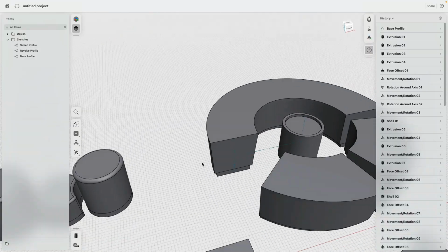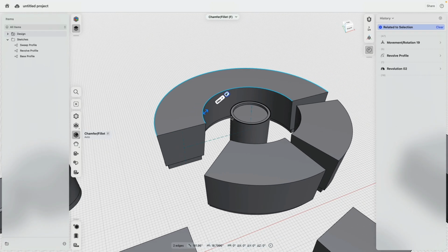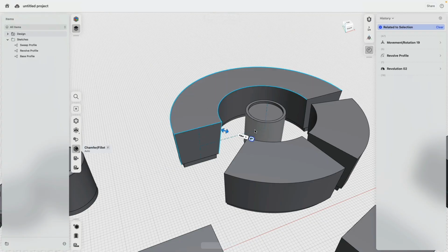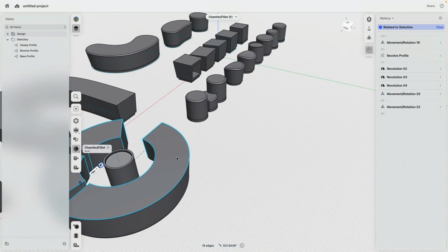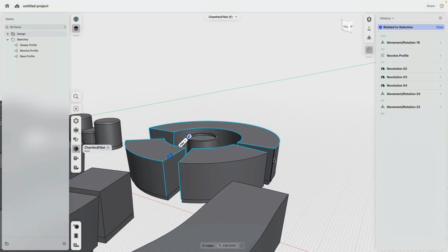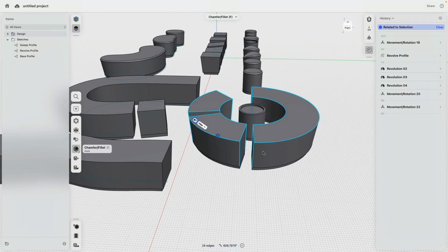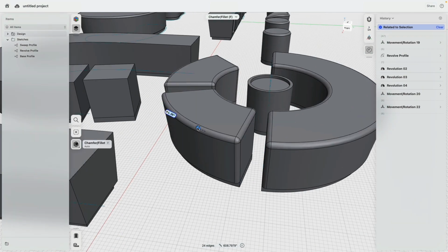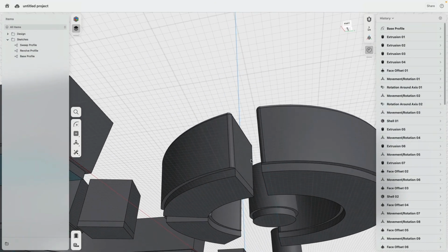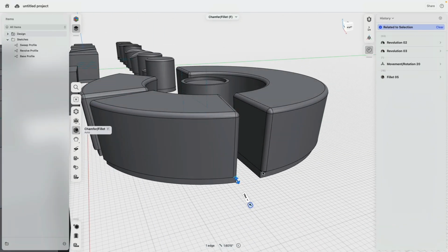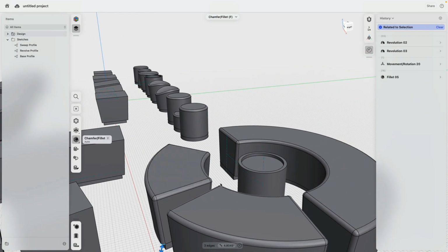Cool. Also here, I will select, in this case, as an example, all those edges. And you see, since I'm considering them all being a family, I simply select all those edges at the same time. Then if I round this, you see we get this triangular edge fillet, and then I have the bottom pieces there and there and there and there, 0.25 to do this rounding.